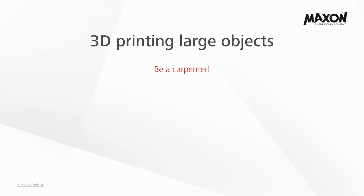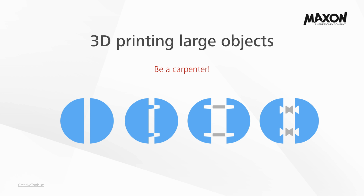If you need to split a model for 3D printing, my advice to you is to think like a traditional carpenter. There is a vast amount of literature on this subject and you can easily go to the library to learn more. My preferred jointing method is to create coaxial holes in each half, and then use dowel pins to secure the parts in place when I glue them together. A quick tip here is to make the holes slightly conical. If you don't want to mess around with tacky glue, you can also use a soldering iron for electronics. Just set the temperature at 200 degrees Celsius and then you can literally melt the two parts together to create a very strong bond.